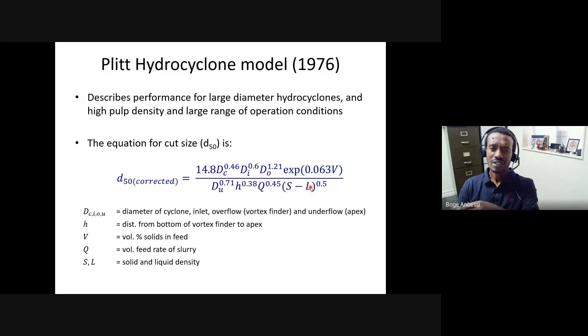Some cyclones use dense media rather than water. So you don't have to use water as a medium; you can use other media. For example, you can make a medium from very fine particles of ferrosilicon or magnetite, or you can even use hydrocarbons, which are not really popular at this stage because they're toxic.